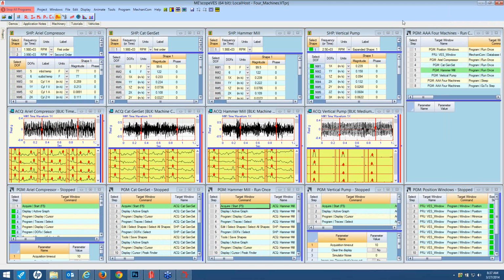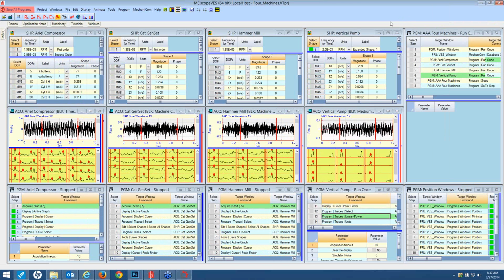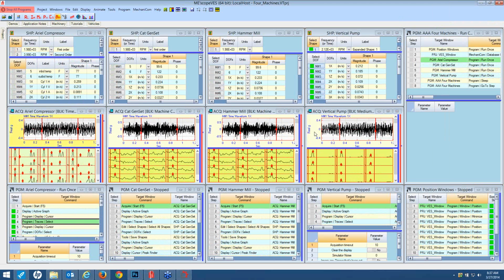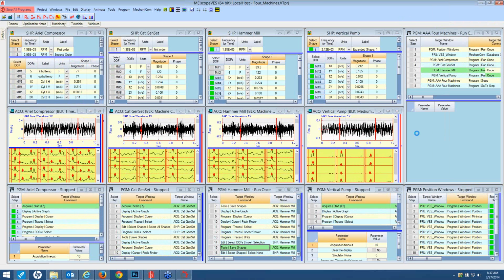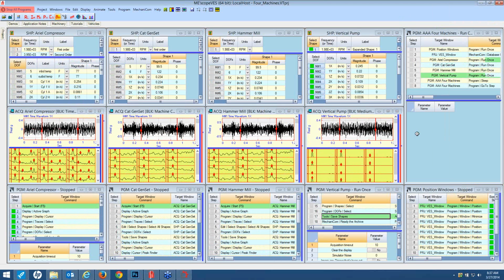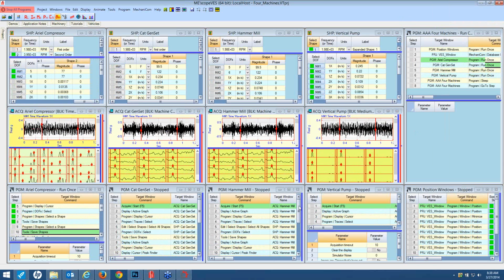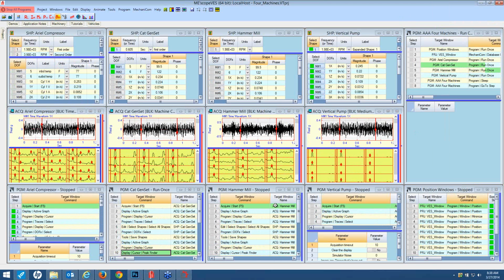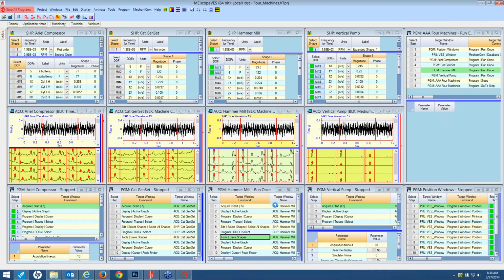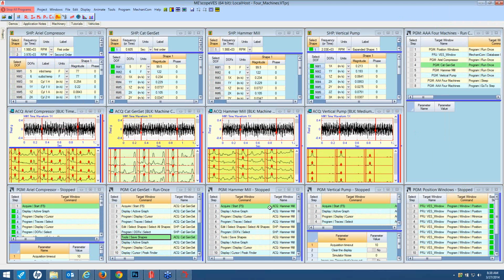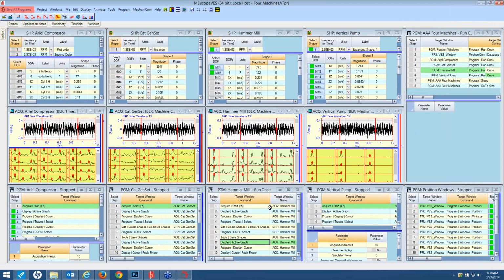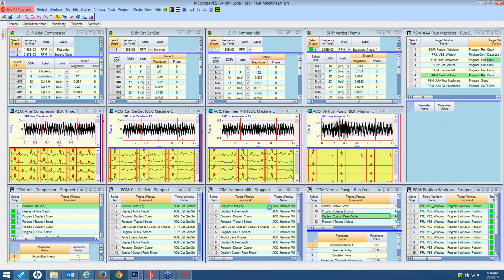Upon acquisition, there are acquisitions running here along this middle section. These are the acquisition windows within MeScope. We're doing 3 averages, and each one has a macro program built into it, running through the different tools within MeScope. All of these are doing ODS, and some of them are doing multiple order tracking. I just wanted to give you a glance of what's going on under the hood and what is actually being done when your data is acquired and post-processed prior to being pushed into the database.